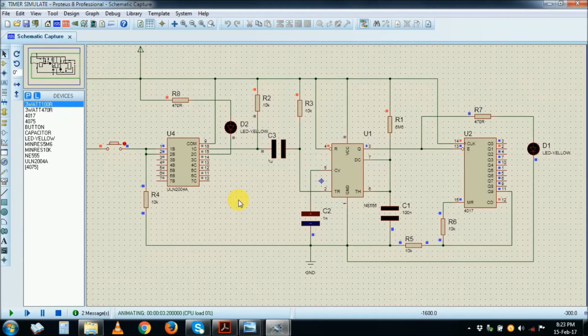Right, because normally when you switch on, the power of the ICs is in any position, so this timer output will be high when you just power the circuits, and then it will go low. That's why it is stepping to number 2, but that's not an issue to worry about much. So if I press here, which will be a pulse, you can check that the moment I press here, this one will come on and this one will come on and off, and it steps to number 4. Then if I press here, steps to number 7. I press again, steps to number 10.